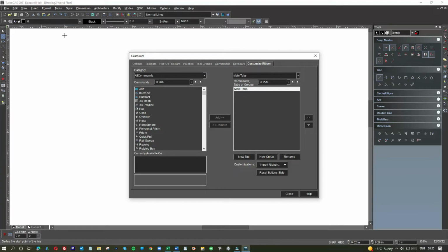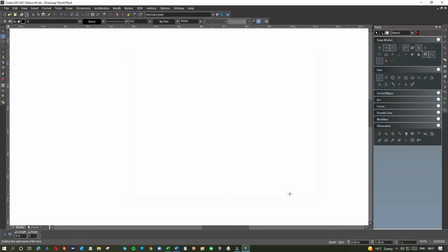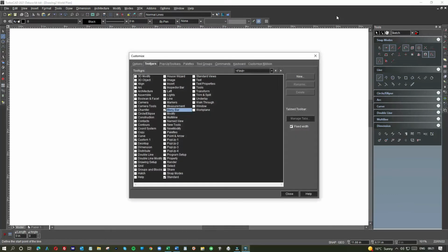But before we use it, let me show you an even simpler way of doing the same thing. It's important to understand early on when using TurboCAD that there are usually more than one way of doing anything. Right, so if we use our mouse to hover over the top right of TurboCAD and right click, see what happens. We have our Customise menu, so it's much simpler than using the 2 or 3 steps on the drop down menu from Tools. So remember, you can either drill down the Tools menu or take the simple route of right clicking the mouse when over the blank space